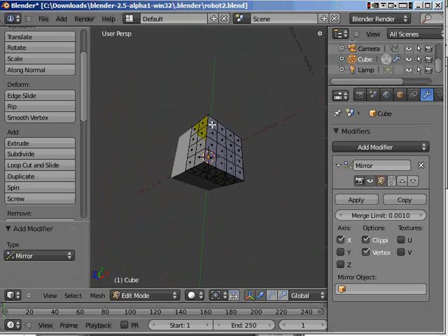We're looking for the side that has all squares. We're looking for this side right over here. That's the right hand side of the box. Then we're going to end up selecting this square right up here. I've done that by right clicking, but of course you can command click. Now to select that square, we're moving on to the next step, which is extruding it out.